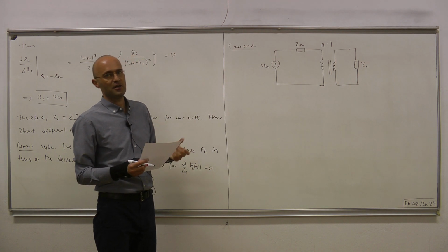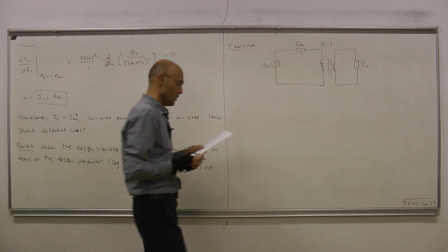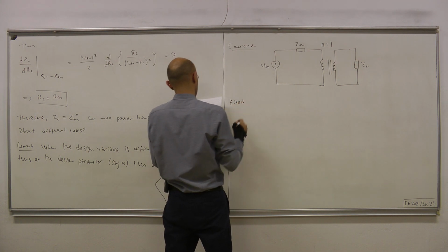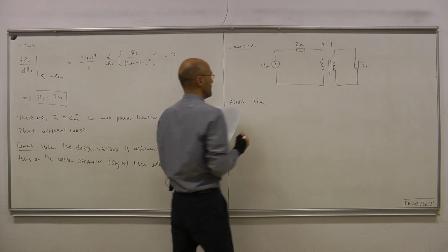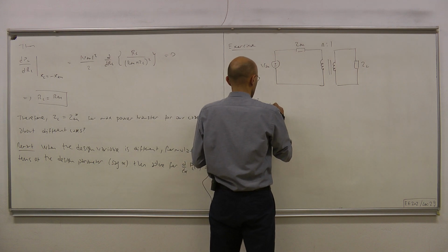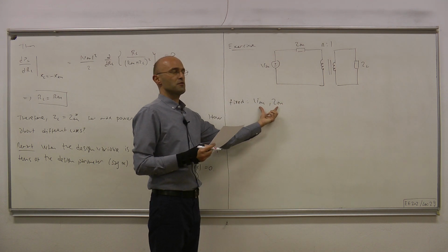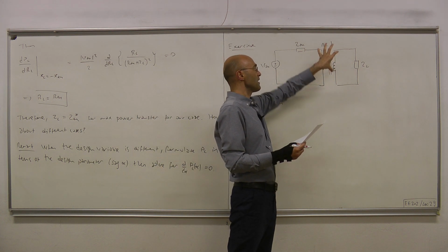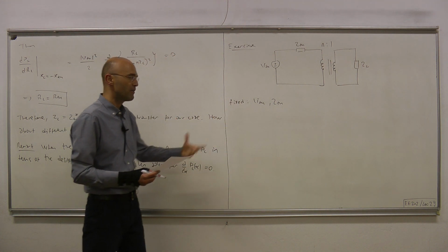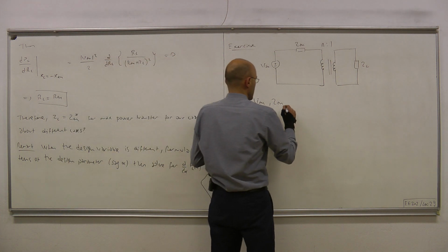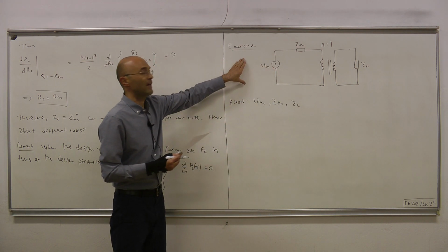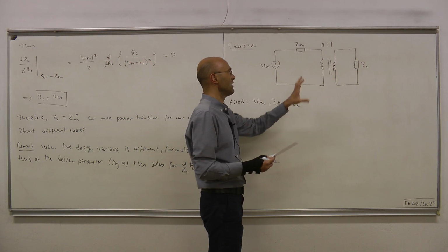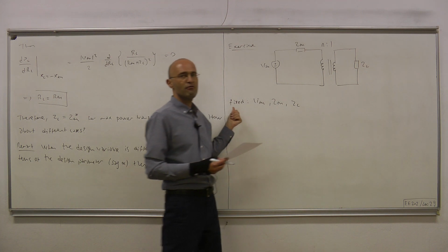Now this becomes another maximization problem. So in this case we have the following quantities as fixed. V Thevenin is fixed, Z Thevenin is fixed, due to the obvious reason that we cannot interfere with the circuit that our load is connected to. That's a very reasonable assumption. And then in this case I want to emphasize, we cannot also get inside our load impedance. So ZL is a closed box. So ZL is also fixed.